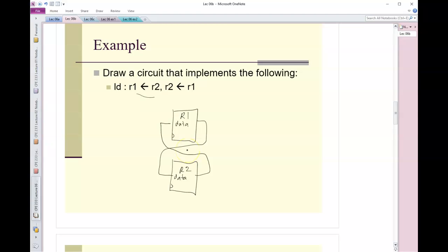Also, this transition of data is going to happen when the load signal is asserted, so I'll put a load signal on these also, and I'm going to call that done. Another thing to notice in this circuit is there's really no notion of data widths. It's sort of implied. When you do your circuit, you can certainly toss in your data widths.